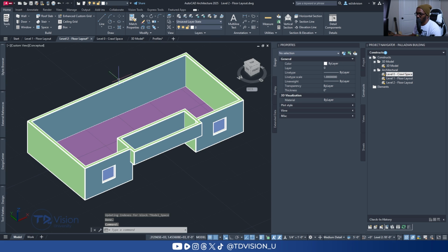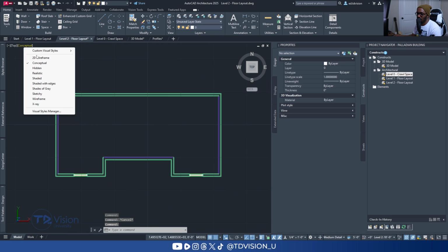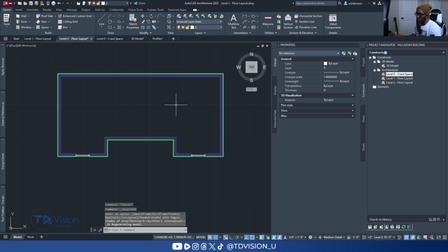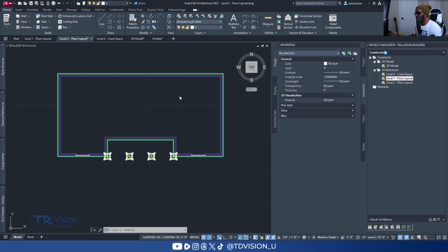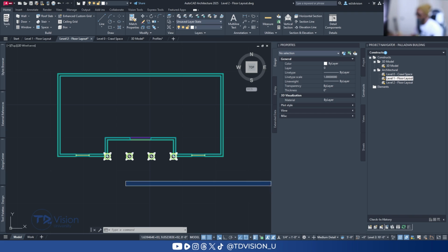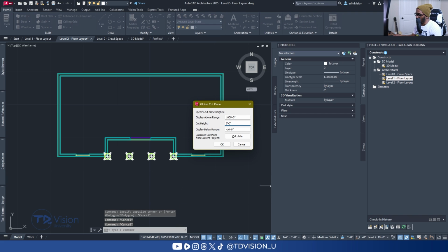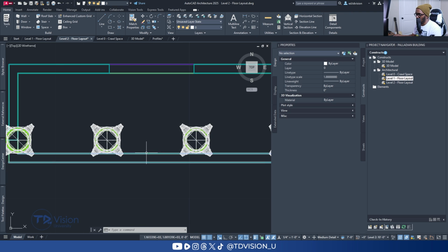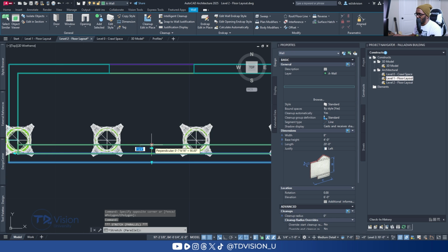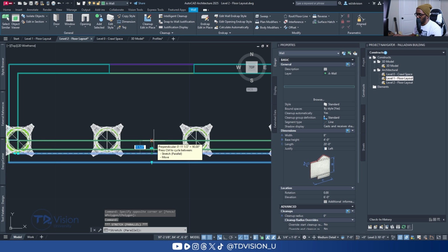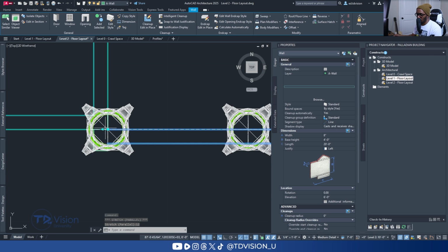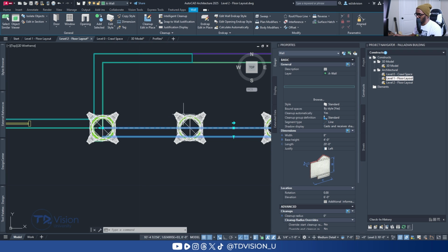So let's come back up here to level 2 and we'll go to the top view and 2D wireframe. And let's bring in the lower floor so we can see those columns. Also let's raise our cutting plane a little bit higher since we raised those walls up. We'll probably need to put this at 7 feet. Then we'll grab this wall here and pull it back maybe about 12 inches. Yeah, so that's how that's going to look right there.